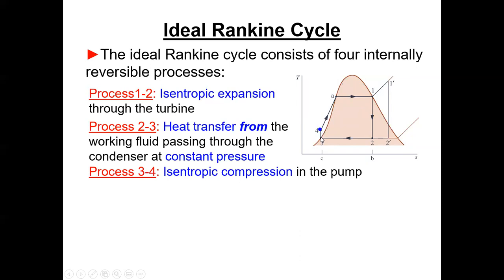That's not heating, that's compressing in the pump, increasing the pressure. It's really the pump in the Rankine cycle that establishes the high pressure that is maintained in the boiler. Because of pressure losses, you have to pump it to a higher pressure than you really want inside the boiler. But it's that pump that establishes that pressure.